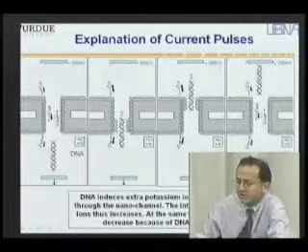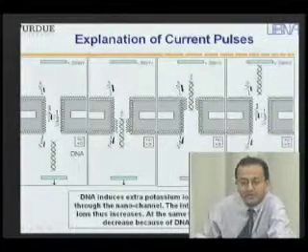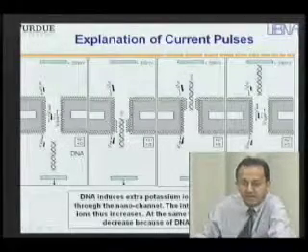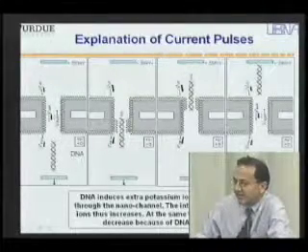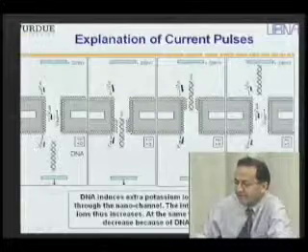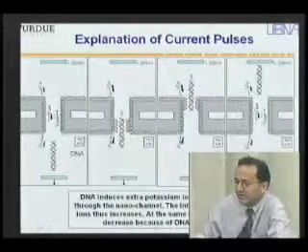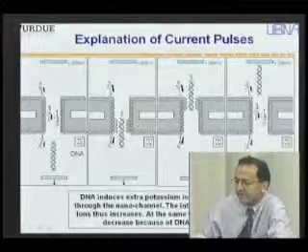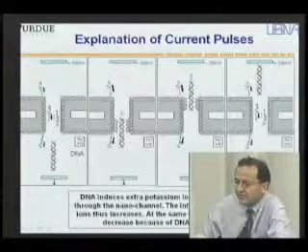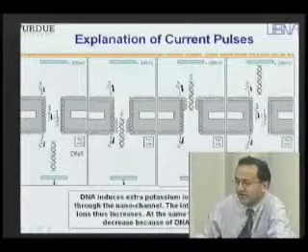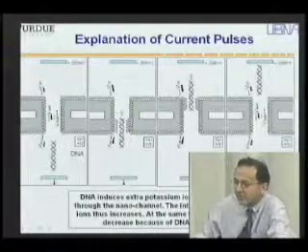They have these silanol groups which get negatively charged, and these negatively charged groups would have a positive ion accumulation close to the surface. Now, DNA has a negative charge on its backbone, so as the DNA moves through, it could be possible that it accumulates that positive ionic charge, and the current that's going through that mobile charge layer then increases, resulting in a net increase in current flow.